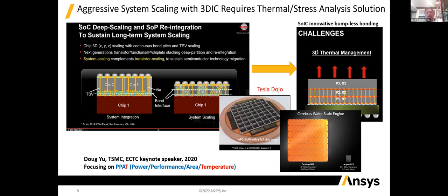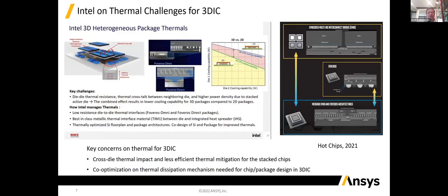And there are other styles of design, including chip on wafer, all the way to the Cerebras design, using the whole wafer as a design, including trillions of transistors, where the vertical voltage regulator for the power delivery and the thermal mitigation have to go vertically at every location of the surface. So Intel recognized the same problem.